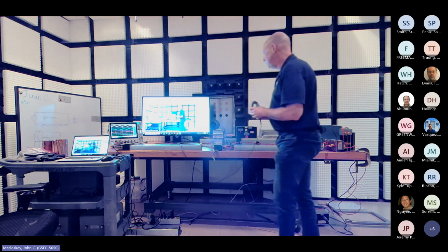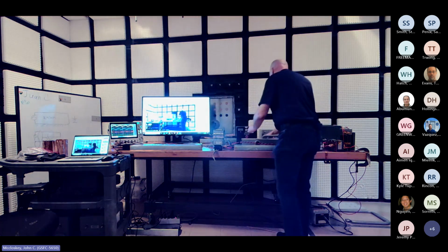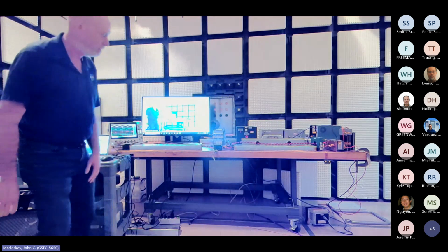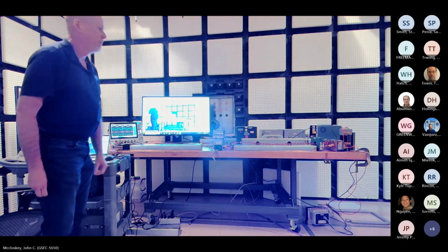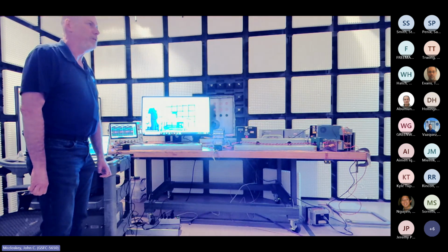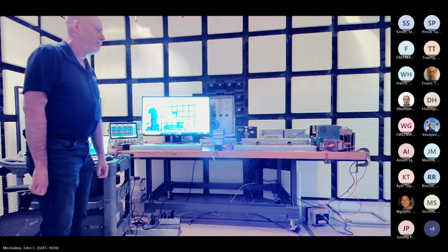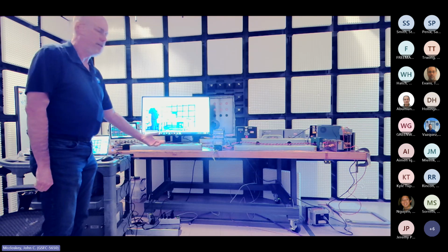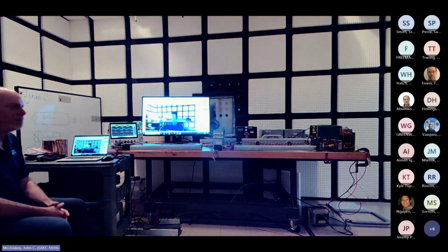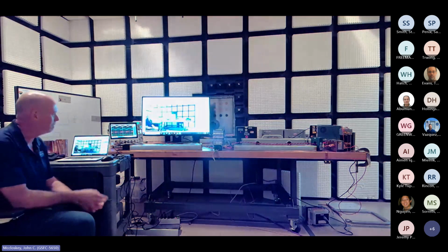So yeah, depending on the frequency range, as Rob just said, with a traditional EMI receiver, it might take a few minutes, 5 minutes. FFT is seconds. Now, okay, an FFT machine is a couple $100,000. Not everybody has one of those, but the point is that even if you have a standard EMI receiver or a spectrum analyzer, you can do these measurements in a couple minutes, and they give you invaluable information about what cables in your setup might be the noisy one, and what you might be able to do about it.